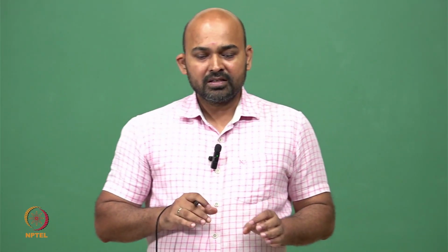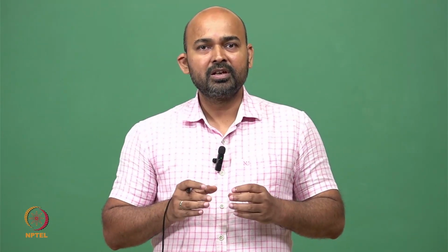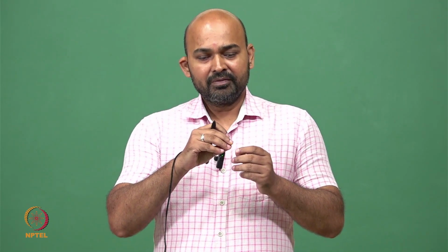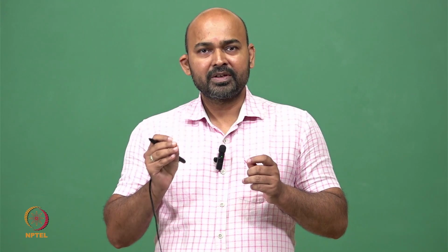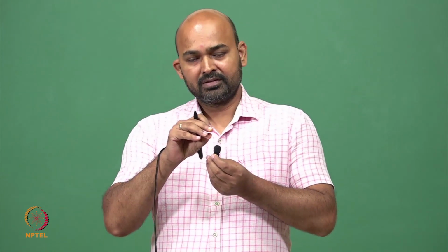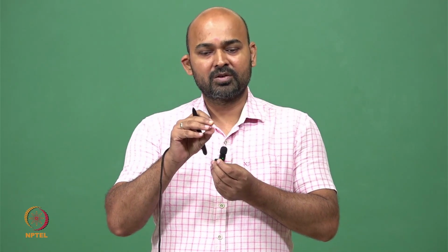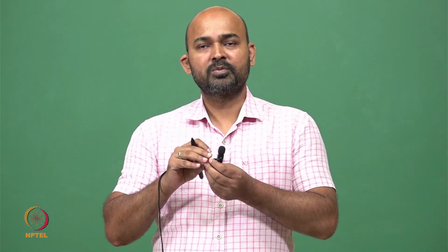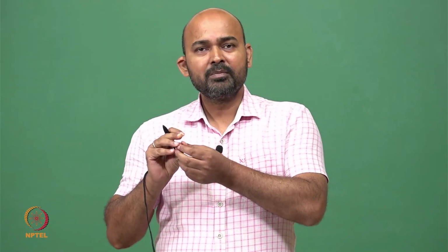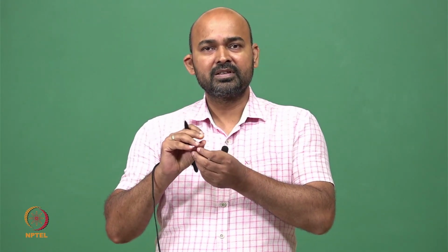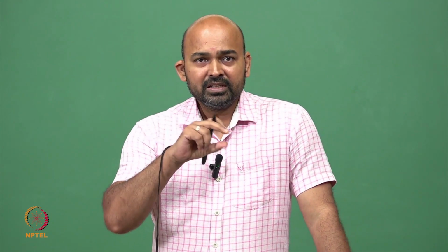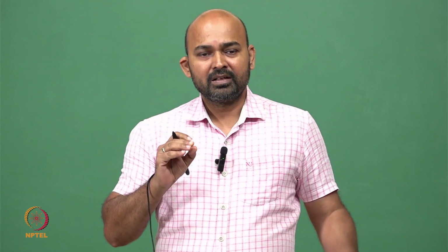In the MI sensor, this is very much similar to the previous sensor. In the previous sensor, we have two arms. One is the reference arm, one is the sensing arm, and this reference arm is kept constant and the sensing arm is exposed to the measurand. At the output, we again combine these sensing and reference arms to get a common output. If we see closely, this structure is very symmetrical.